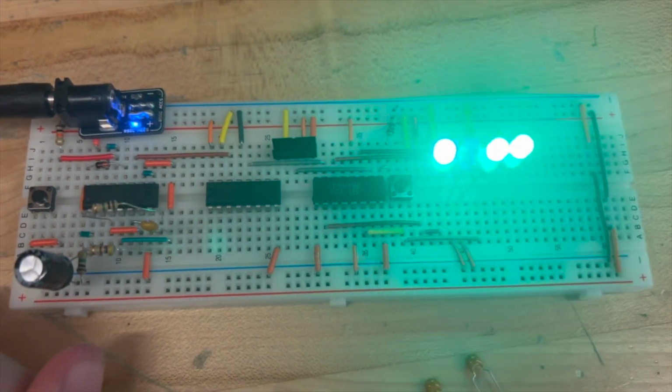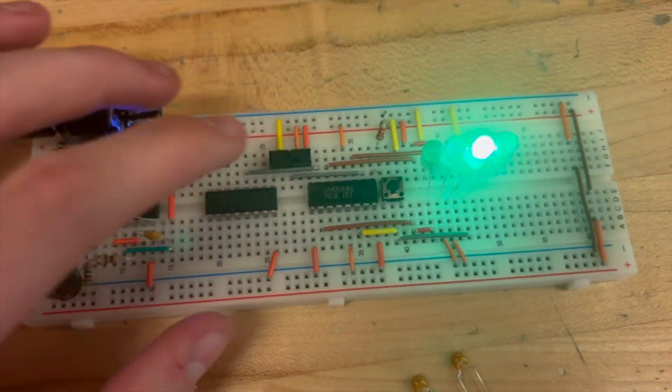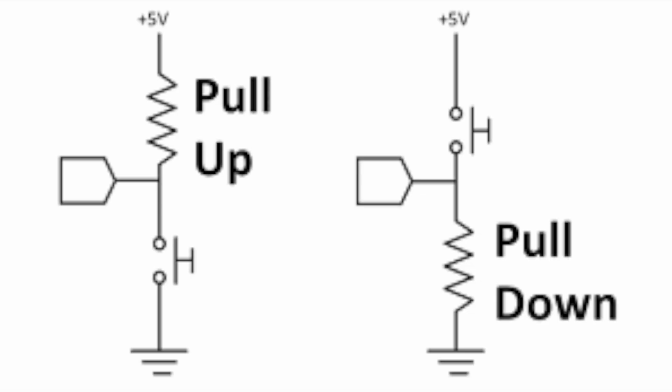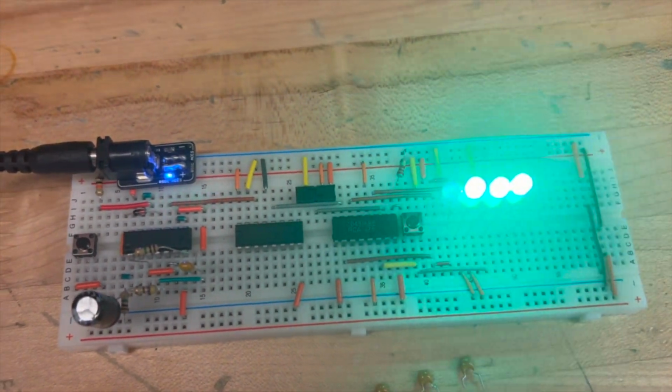Here I am changing whether it's an up or down count by slotting my switch to the up-down pin on the 4017. Here I use another pull-down switch to enable the reset pin. This resets the count to 0 and starts counting all over again.